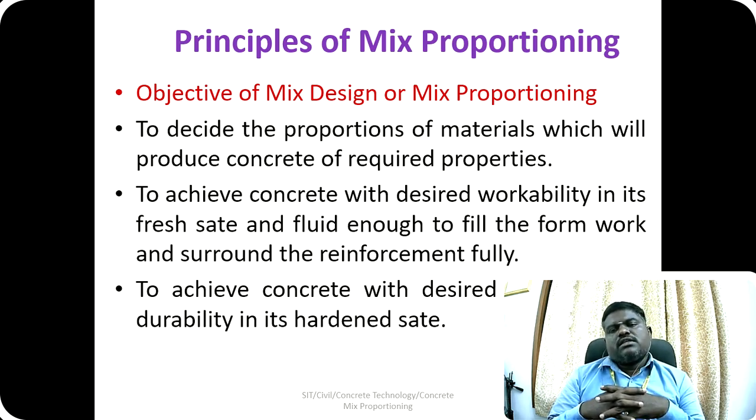The second thing is that in the fresh state the concrete should be workable and its flowability should be good. Then only will the concrete easily flow through the reinforcement and spread all over it, making a good concrete. If the concrete is not workable, the mix will be a dry mix and it is hard to make a structure or member with the desired shape.